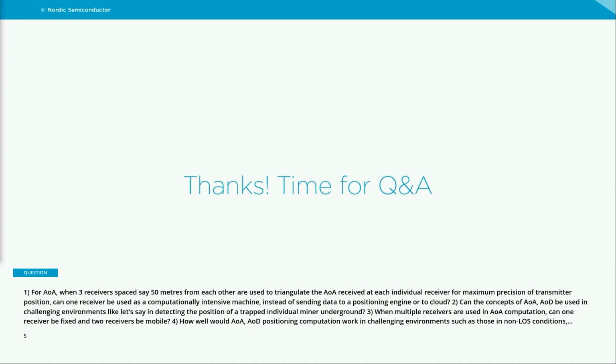So it is possible to do the calculation for the angle resolution inside the device. It is also possible to use one of the microcontrollers to collect angle data from multiple units and then do the calculation for where things are in 3D space. The question is just how many units you want to track and how fast you want the report rate to be, because it's all about how much processing power you have available. So everything is possible. It's just software. It may not give you the performance that you require.